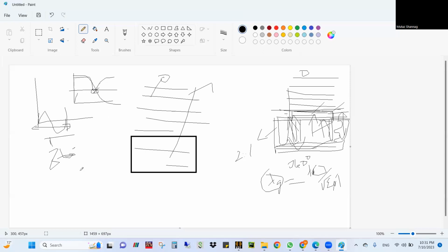Okay, so what is S11? S11 is nothing but reflected voltage divided by incident voltage, right? Sorry, Professor, for the interruption. Should there always be a zero crossing between the reflection and the phase? No, I will explain it. So we define it as V reflected divided by V incident, right? That is how we define it basically.